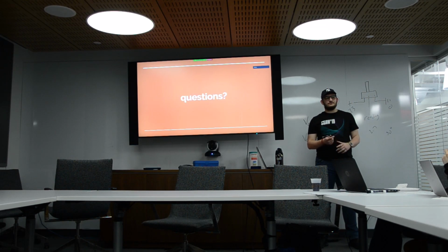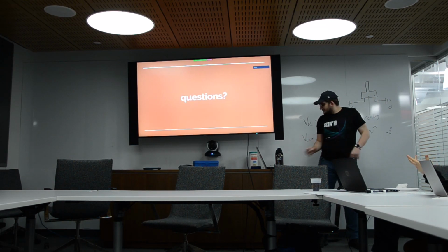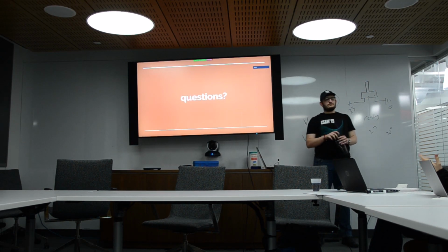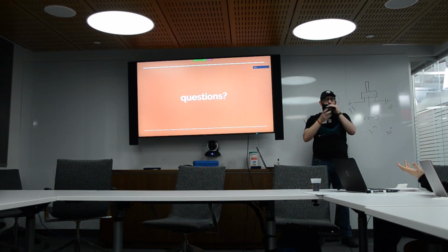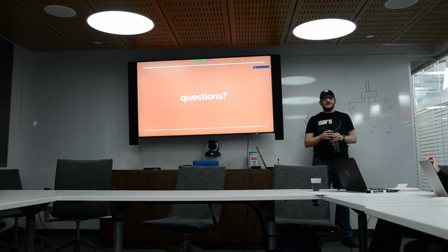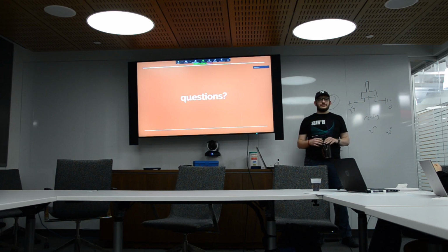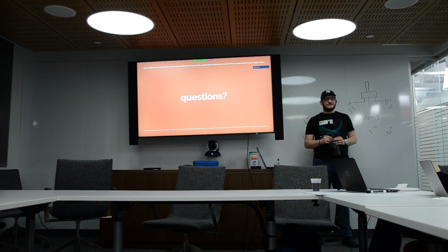Yeah, so if one were writing firmware and wanted a good programming language to use, what would you suggest? Firmware is still predominantly written in C, and the reason for that is the toolchains for these devices. It's not like you're writing for a desktop where you just have GCC and it just works. You need toolchains for whatever devices you're using, and most of them just include a fork of GCC that has support for that particular processor architecture and peripheral set. So you're often just tied to the fact that that's all the tooling that you get.